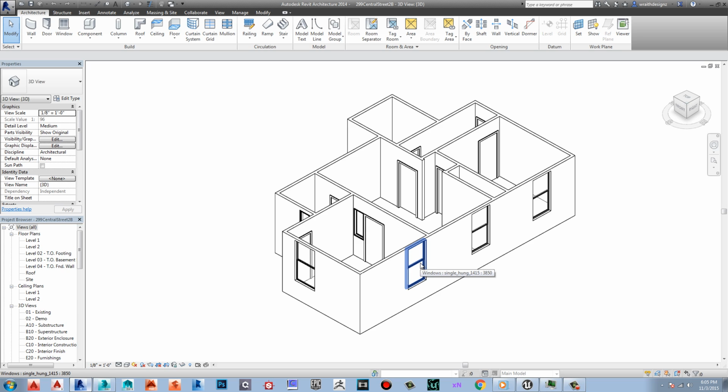The reason I do it this way is because if you try to take the entire model as is, try to UV it, try to light map it, things like that, it takes forever, causes problems, and it may crash Unreal Engine 4 when you try to import the whole thing. So depending on what you're doing, it might not. You might have a better system, it might not. But Revit was made for architectural design, not necessarily made for gaming. So there will be a lot of high polys and vertices because these are actual manufactured windows. So let me show you that in 3ds Max.